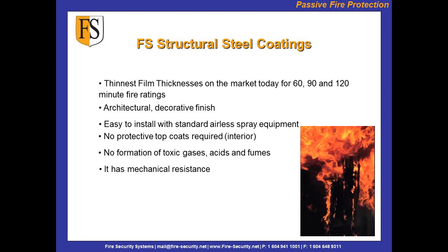Now, pre-erected steel is when it's sitting in the blast area and it's just been primed at the shop. Our installers can come in and spray that steel while it's on the floor. It's not erected in its structure. That's a very economical, very cost-effective solution because there's no scaffolding needs, there's no on-site requirements. We come straight to the shop, we spray all the fireproofing onto the steel, and it's fully cured when it leaves.